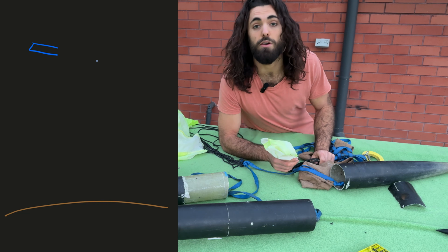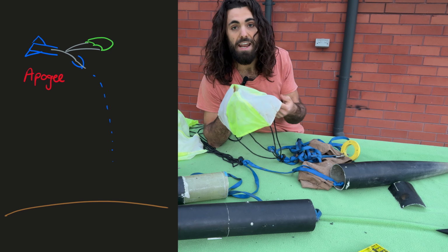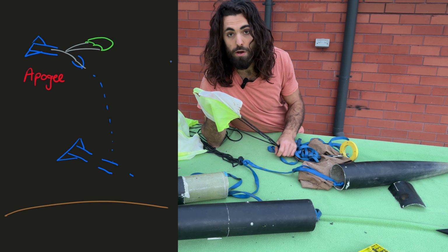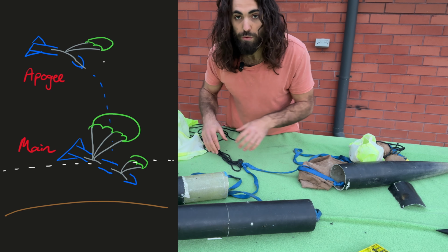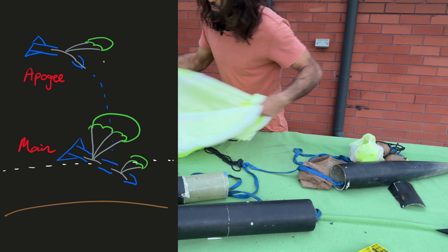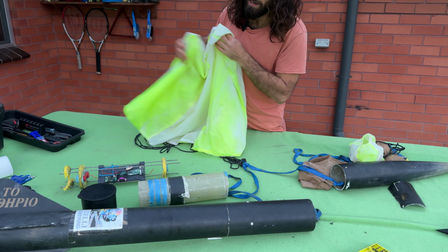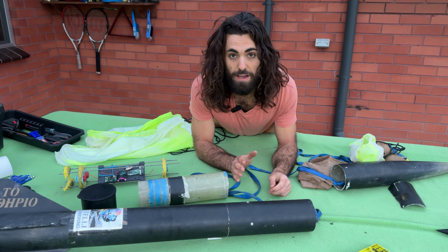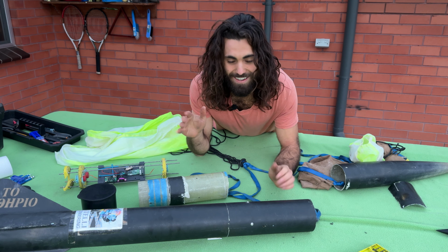For rockets that go to a higher altitude, you typically want to deploy a drogue chute at apogee so it can slow down the rocket as it comes down, and then have a flight computer reading the air pressure to infer altitude, and once it gets to a low enough point, release the main to slow it down to a safe speed. If you don't do this, you're going to be walking 5Ks to get your rocket. As an experienced idiot, trust me, it's not fun doing that.